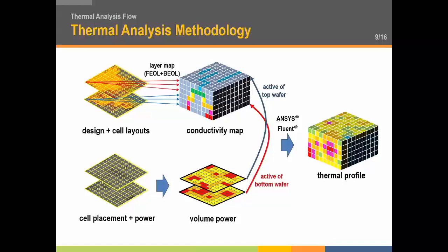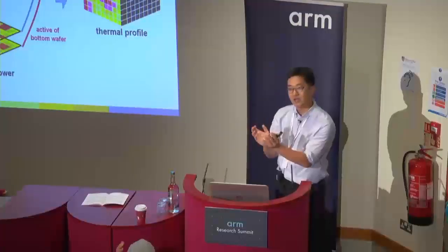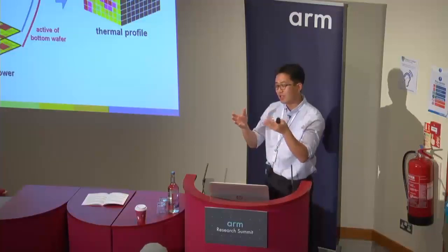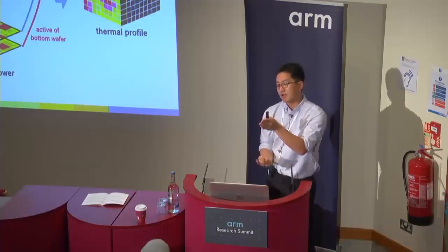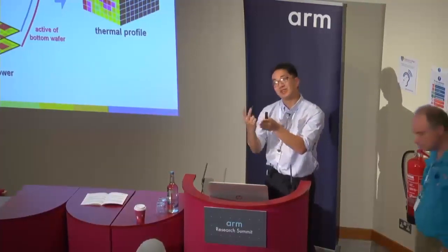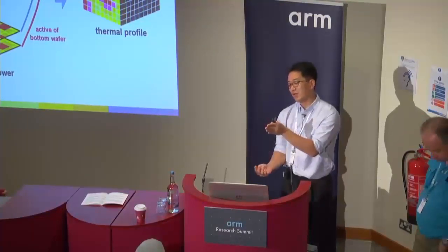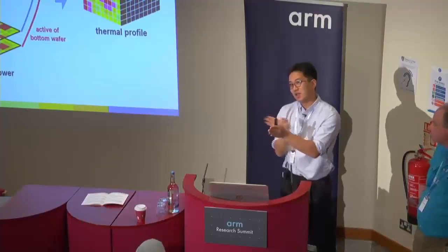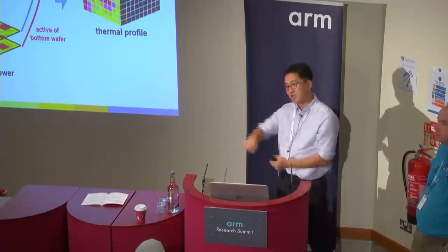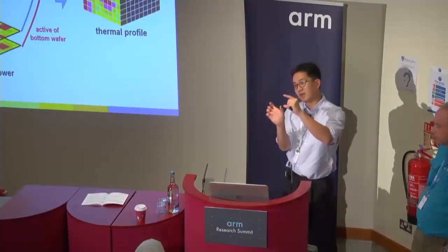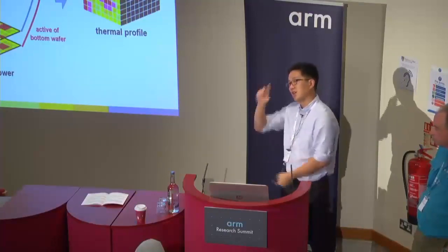If, let's say, in any square half of it is dielectric and half of it is metal, then we calculate the portion of the dielectric and the metal layer, and using that we calculate the parallel thermal conductivity for the vertical direction, and the series thermal resistivity for the lateral conduction, and use those two thermal resistances to represent the cell conductivity.